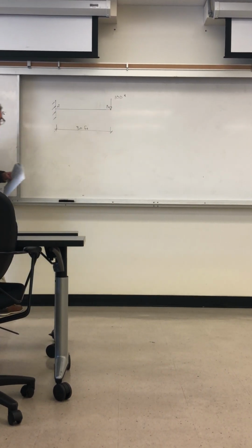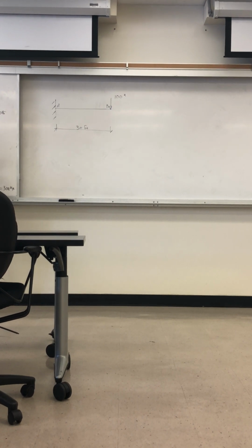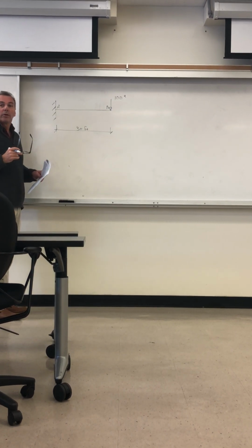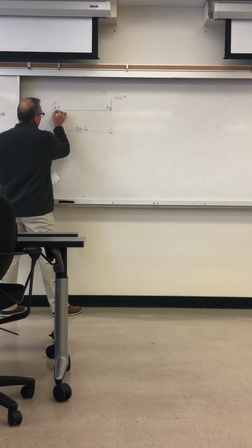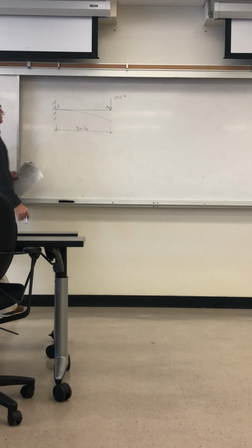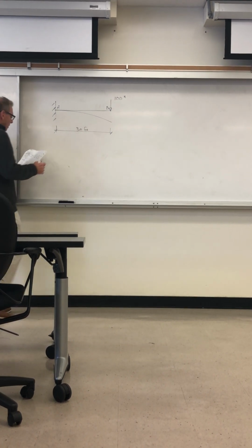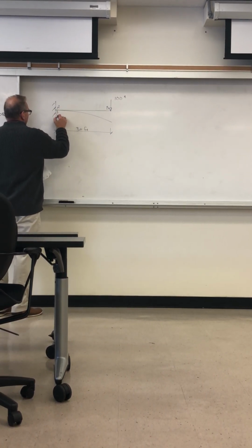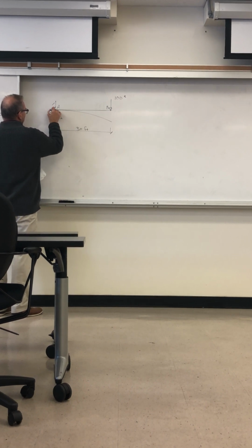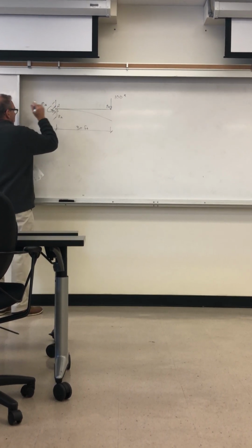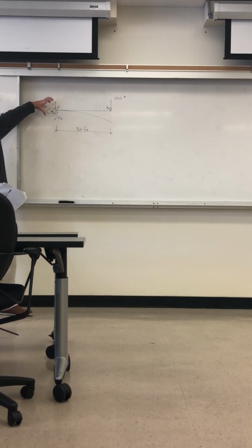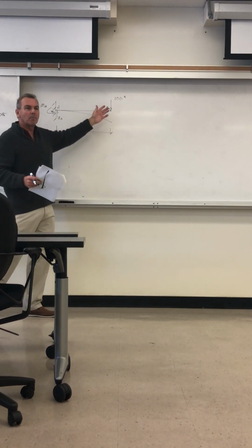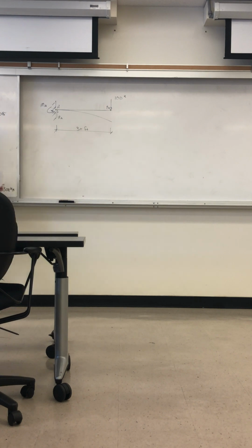Deflected shape. So this is a cantilever, it's fixed at the left side. So there's no displacement and no rotation either. So it comes out, it's a fixed wall by definition, okay? So it's like this, something like that. We have a reaction A. There's no longitudinal reaction and a moment. So there's a moment on the wall. So imagine a moment, it's like my hand doing this, my finger pulling this way, my thumb doing that. That's the direction of the moment. That's the moment that's resisting 100 times